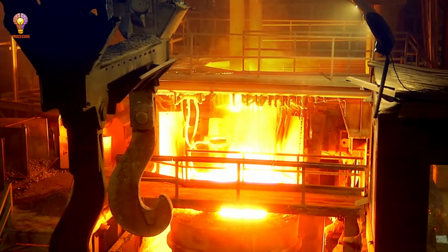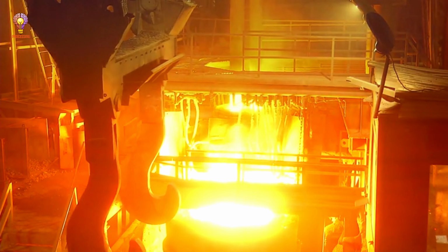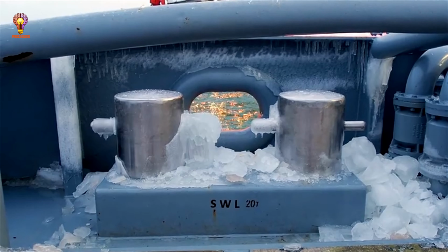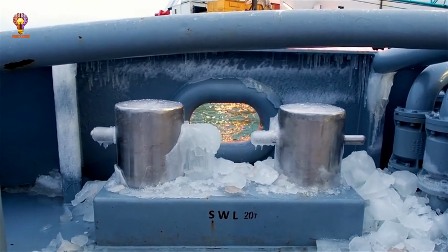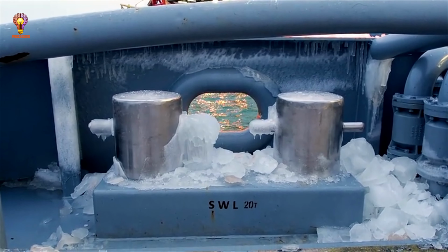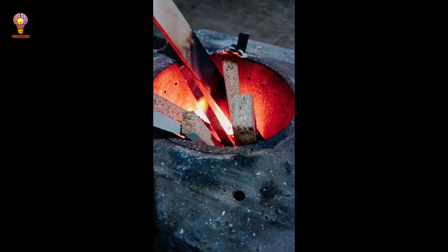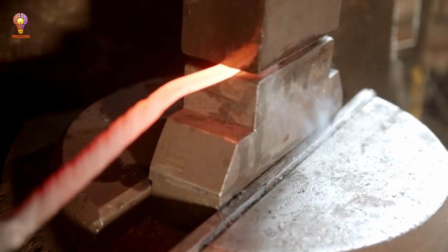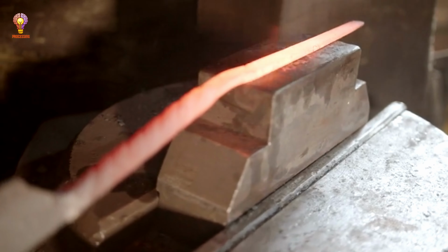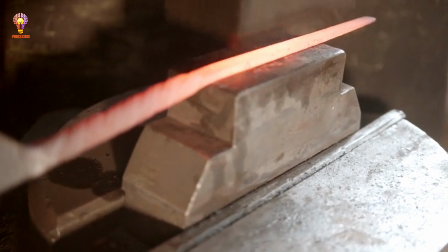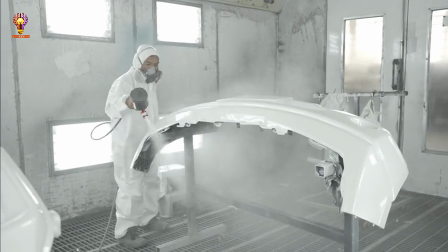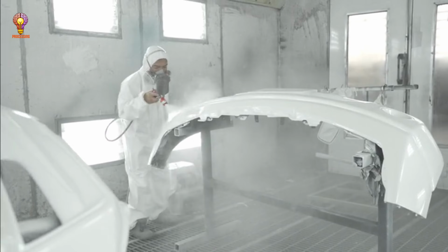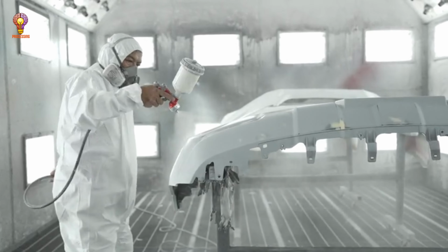Heat treatment. Steel is heated and cooled in a controlled manner to achieve desired properties such as hardness or toughness. Examples include quenching, rapid cooling typically in water or oil, to harden the steel. Tempering, reheating quenched steel to reduce brittleness and improve toughness. Annealing, slowly cooling steel to relieve internal stresses and increase ductility. Coating. Some products, such as automotive steel, may receive coatings like paint, anti-corrosion treatments, or even plastic coatings.